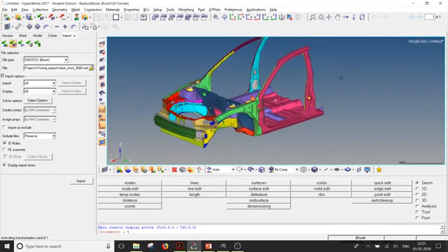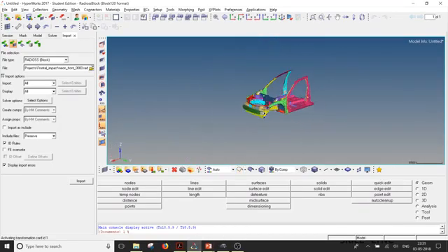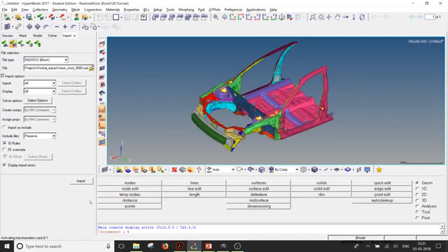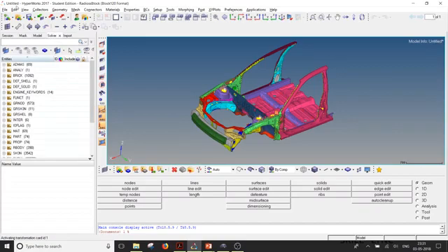Now in HyperMesh, there are a few easier things to do and a few easier things to take care of. Most importantly, whatever you create, always use the solver browser. You can go to View, Browsers, HyperMesh, and Solver Browser. If you click on this, you will get this browser over here, and in that you will see the list of keywords.